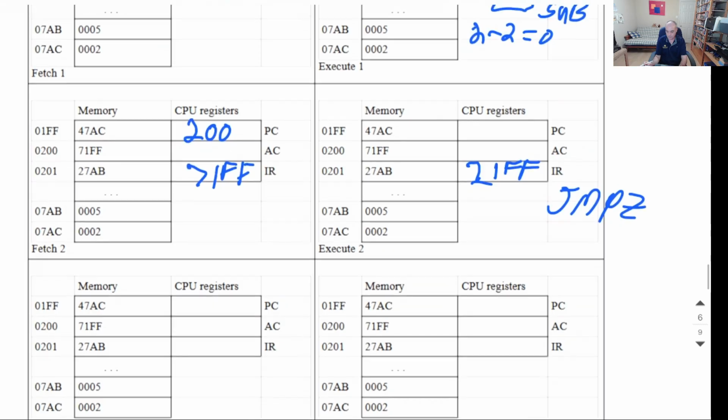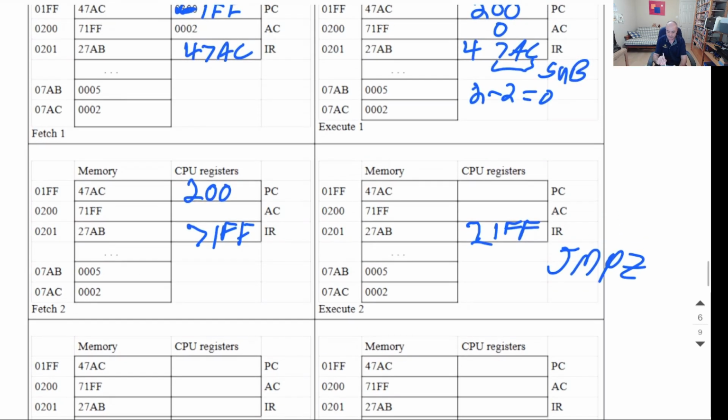So we had a 0 in the accumulator. So basically, in our hexadecimal machine, they make their decision. So the jump 0, the jump on, are conditional jumps. They make the decision based on whatever the current contents of the accumulator are. So since the accumulator is 0, that means the jump is going to be performed, right?